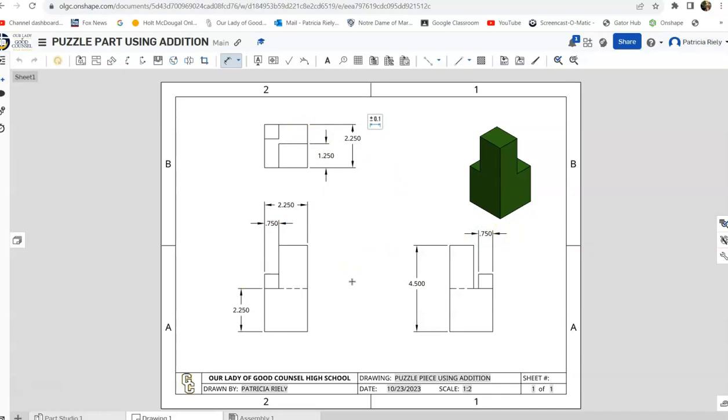So let's look at this. Do we have all of our dimensions? And I believe that we do. So if I gave you these dimensions, you would be able to build that part. Okay? So look at the dimensions. Do I have overall? And do I have the component parts done correctly? I did not dimension to any hidden lines. For the most part, I kept it in the house, except for this one, which I really didn't have an option with given the hidden line. So I think I'm happy with that.